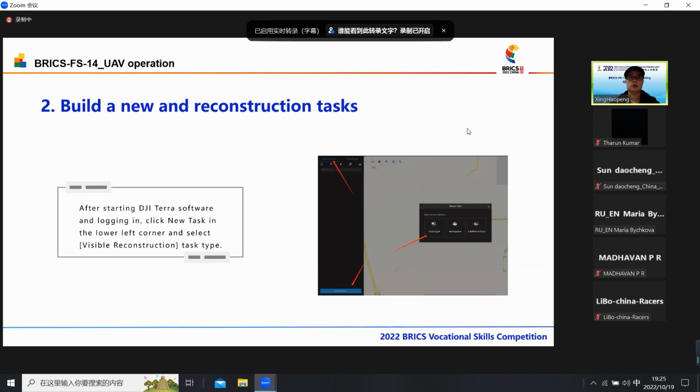Click the detailed information, scroll down to find the 35mm focal length parameter item. Next, double-click the parameter value box on the right to enter the edit mode and enter the correct 35mm focal length parameter.